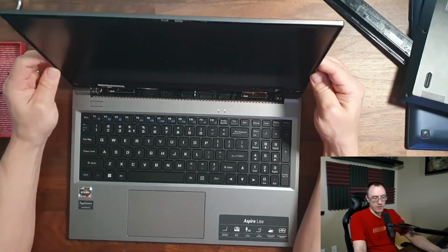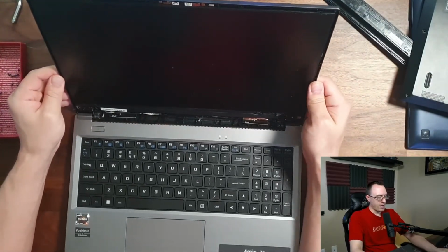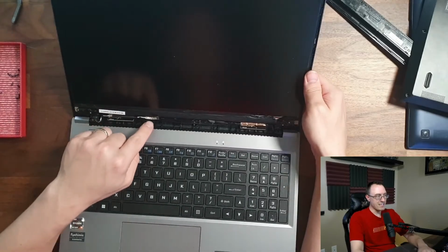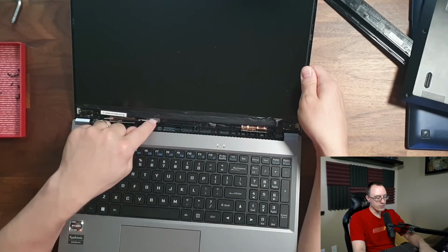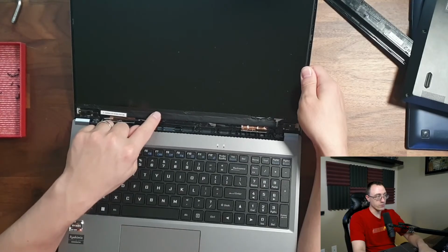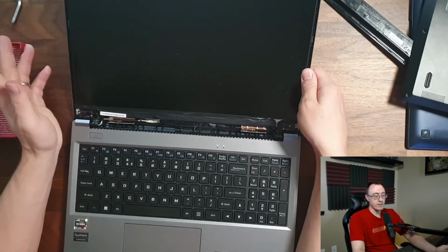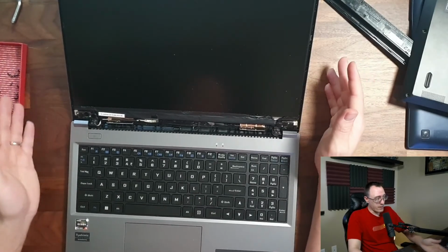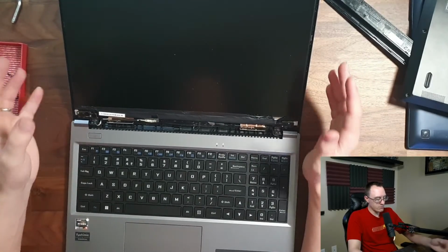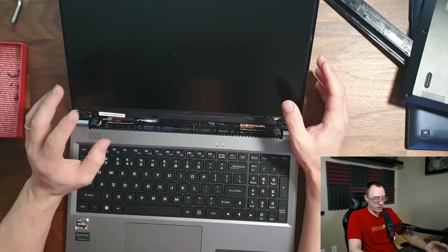So I wouldn't recommend doing that either. But I am concerned that the LCD is maybe disconnected down here somehow, even though it does seem like it's taped in. But if the LCD connection is disabled or disconnected from the actual LCD itself, you also will not get any display. So some of the troubleshooting steps we've talked about, you know, what you do, connect it to HDMI to see if you can get video out. If you can, that means that the video chip itself is okay.